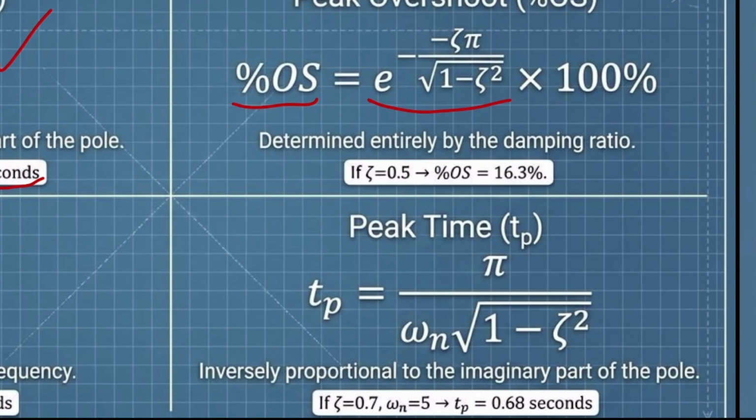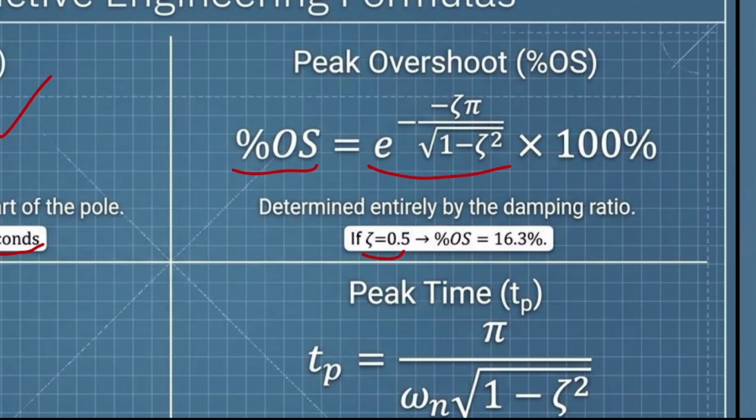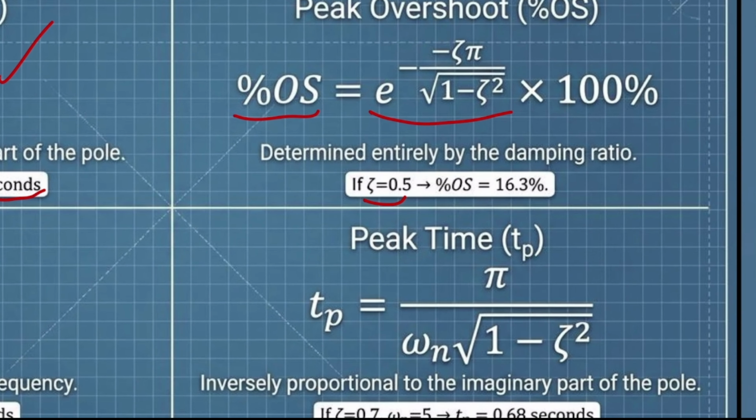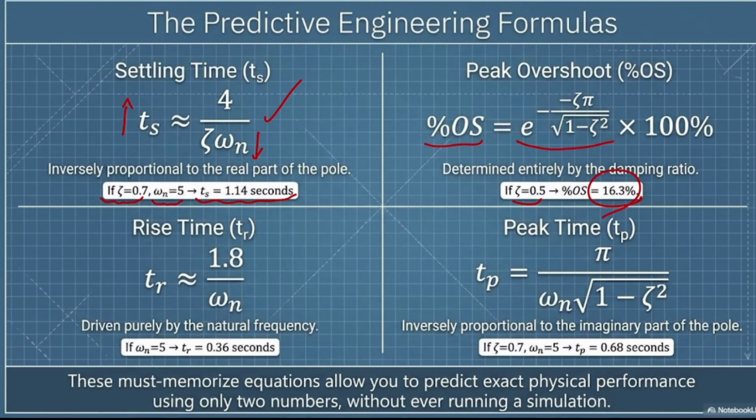So these numbers are going to be a little bit intuitive. The number that most of the time we use, again, is going to be the sweet spot. Imagine that I have the case that my zeta is 0.5, because as you can see, this is a function whose only input is zeta itself, and it is completely related to that. If zeta is considered as 0.5, my overshoot is going to be something around 16.3%.